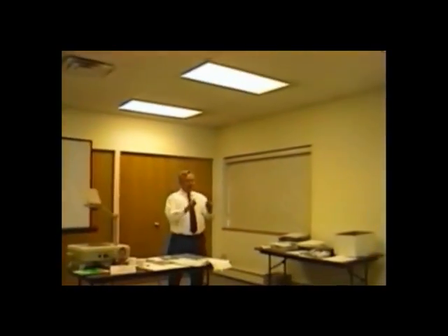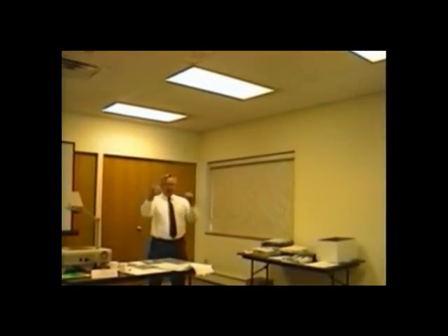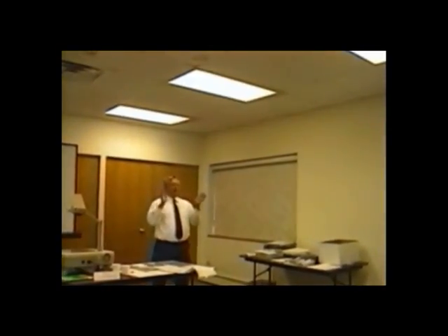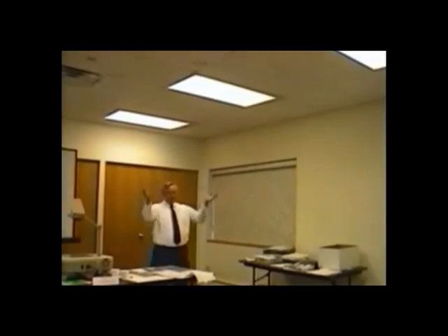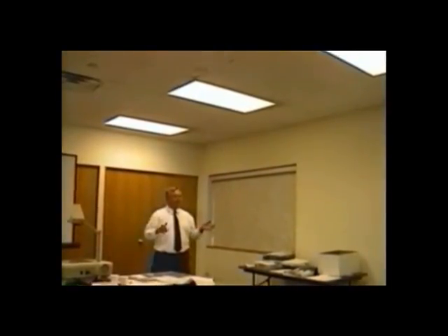Let's stop and talk. What they're telling you there is that all the condensers from Rheem manufacturing, Rheem Ruud Weather King, come completely charged and are set up to handle 25 feet of standard line set. So if it takes X amount of ounces, they add some more, and that'll handle the 25 feet of line set.